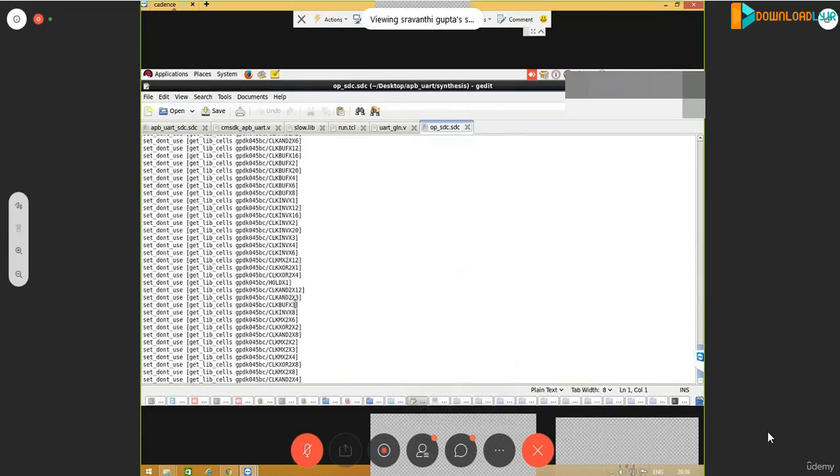And for the lint report, should I follow the same procedure, the greater than symbol? The command in Cadence is report_timing -lint, and you can use the same command when you are implementing also. For dumping also, you can use the greater than symbol and the file name where you want to dump.